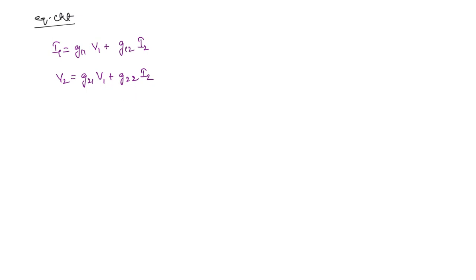On the input side you are going to get a circuit element, since this is the voltage V1 here and current I1 is flowing, G11 element you can take as a circuit element. The other term you will have to use a dependent source because it is dependent on the current in the output side. So this is G12 I2.